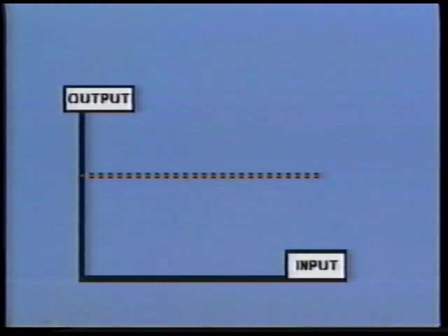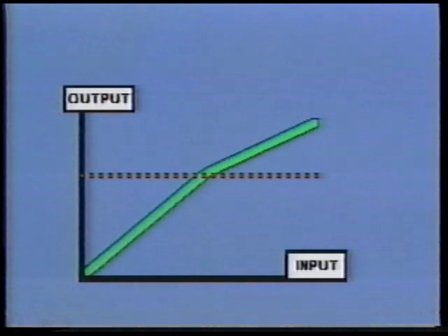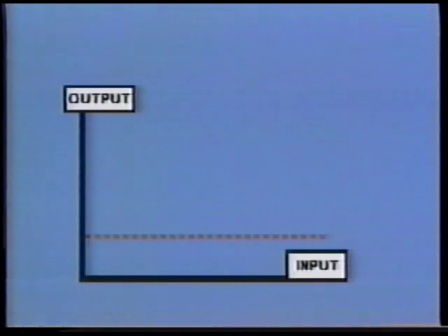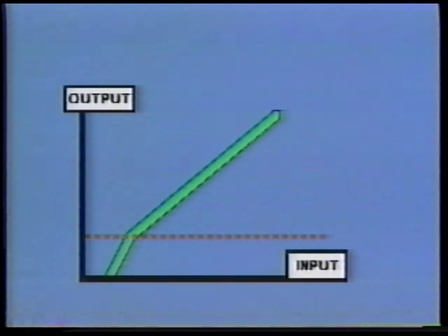The performance of all VGAs is defined by several variables. The threshold is the level at which the gain reduction begins to occur. Compressors and limiters turn down the gain when the input signal goes over the threshold. Expanders and gates turn down the gain on the signal when the input goes below the threshold.